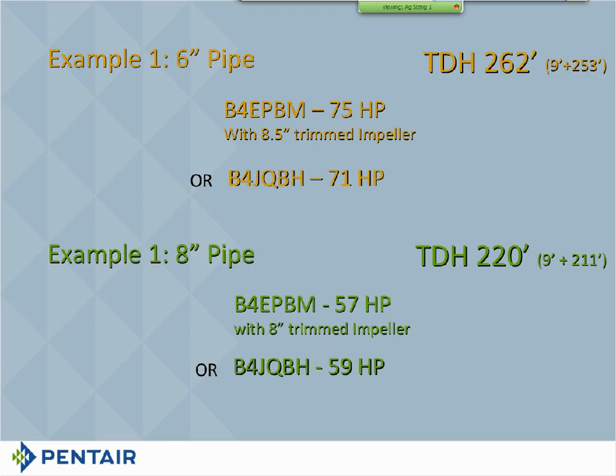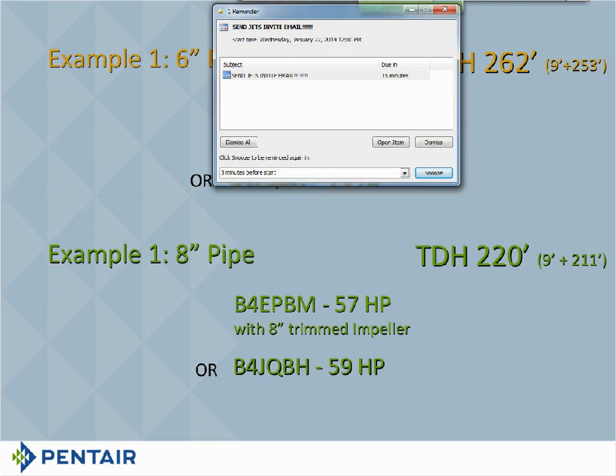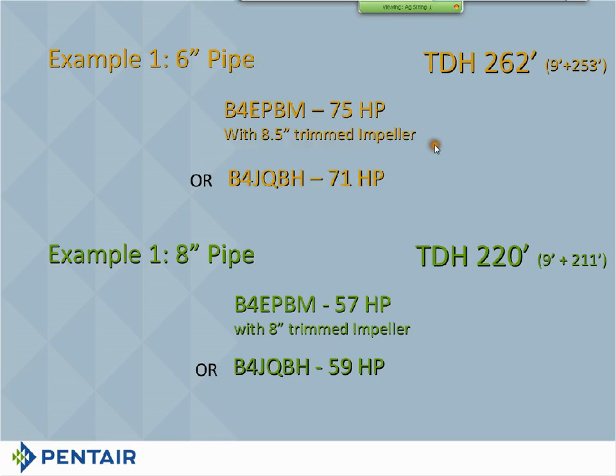Now, what we need to do at this point to help him to understand what's going on is we need to know what is the cost of electricity. And I will tell you a formula. It's not 100% accurate, but at least it gets you in the ball field here. When it comes to diesel fuel, the rule says that it's 10 horsepower per gallon per hour. So for every 10 horsepower I'm running, I'm going to use about a gallon of fuel per hour of running. Okay?